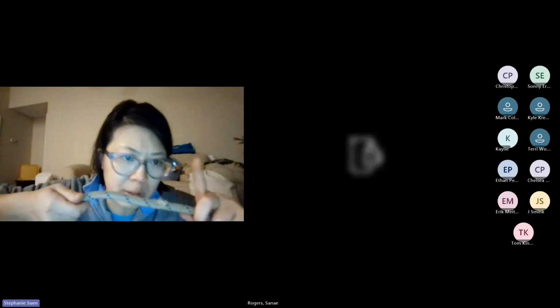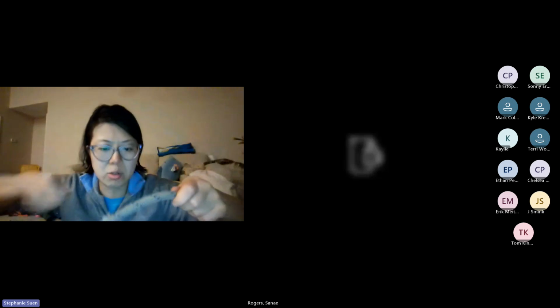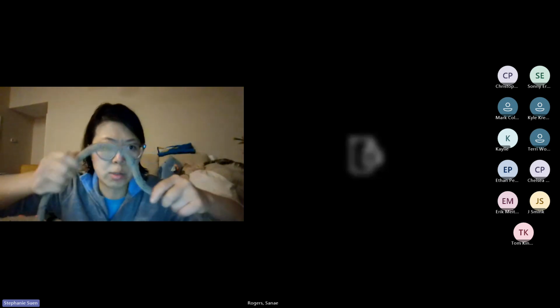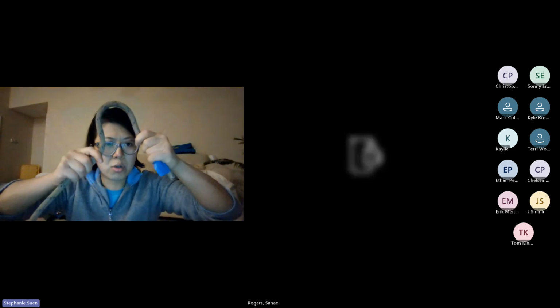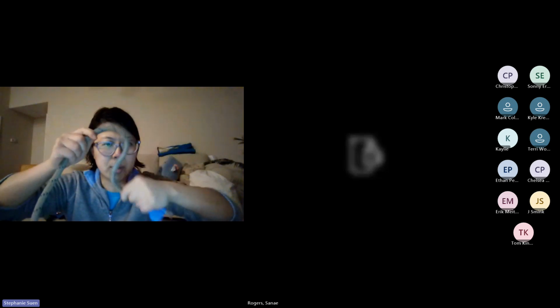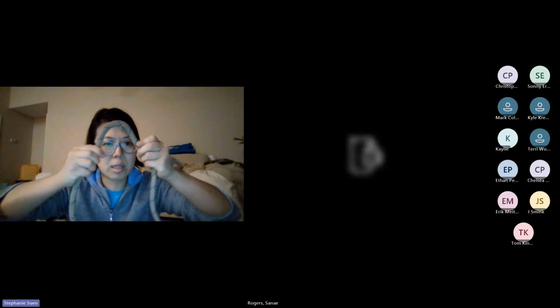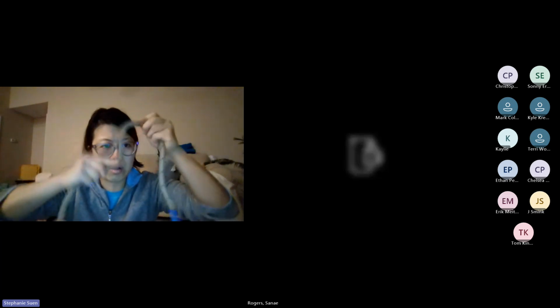And this is a deliberately core shot rope. This didn't come from an accident. We core shot it on purpose using a little tool driven into it to give an example. But as I'm doing my rope inspection, you can see I've got that nice bend right here. It flows through my hands. I go to the next segment and you see this little bend here, and it feels weird.